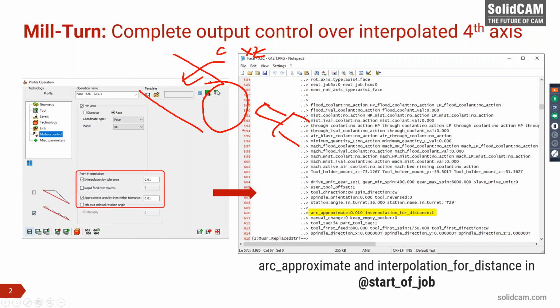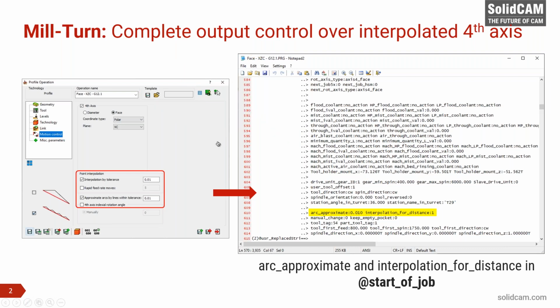Some of them have the cycle for Cartesian input. Some of them don't have it, as this is optional, and not all machines have it. In the case when your machine doesn't have this function, like in FANUC, everybody who is familiar with FANUC knows it's 12.1. Besides the Cartesian input of the coordinates, it also allows you to synchronize the linear and rotary axis feeds.